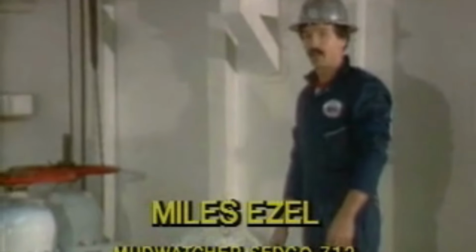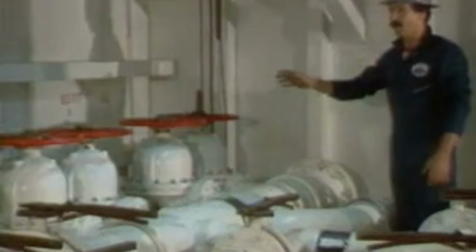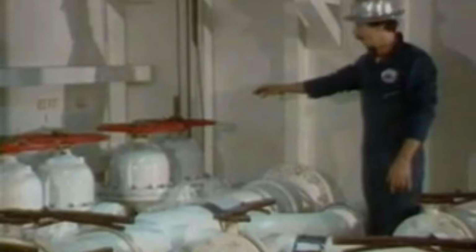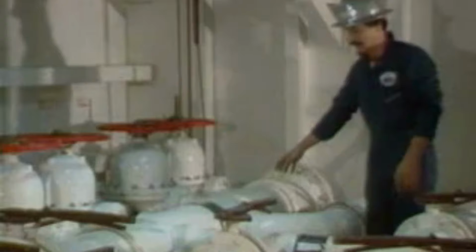After getting the weight material over to my surge tank, now I'm going to have to weight up my kill pit to get a pit of kill mud. I have my suction valve open with all the other suction valves to the various pits closed. The pump I'm going to use is mud mixing pump number 1, which is located right here. I'm going to be drawing mud from my kill pit through this suction valve, through this 12-inch line.